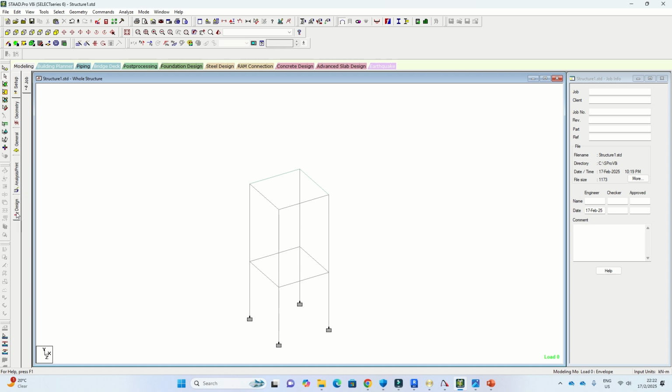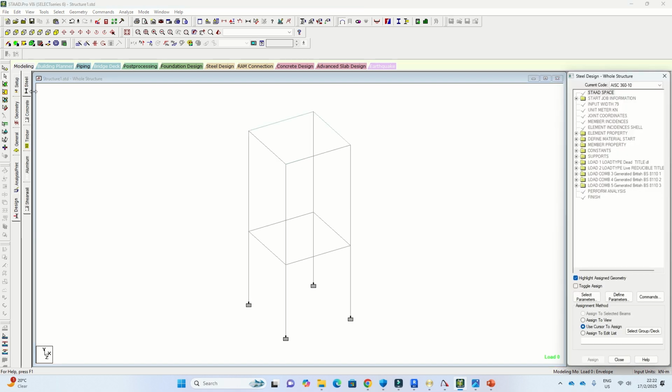Now let's go to design. You click here on design, then you go directly to concrete. There's no steel here, it's just concrete. So I went to concrete here. I'm going to click here and select CP65. This one differs from the BS8110 in only 71 points. It's the closest that we have to the British standard that we use here in this app. Okay, now I'm going to use this one.